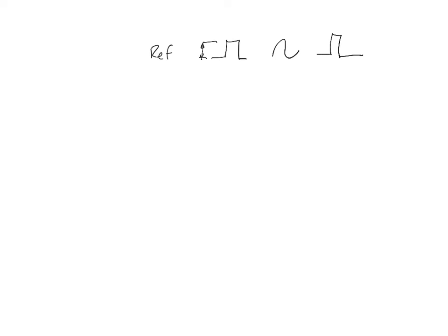That's too small. There are specs that you can look up in the manual and how big the amplitude needs to be. And also, if it's a pulse like this, say, what the duty cycle of the pulses are, what's the minimum pulse time, all that kind of thing. If you're going to use anything other than a sine wave or a square wave of reasonable size, say, a volt or something like that, consult your lock-in manual as to what the signal requirements are for the reference phase.